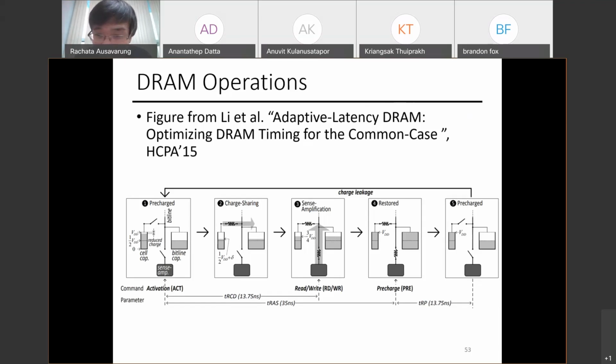Okay, so can we only write data on the DRAM row? Yes. You need to write the data on the row buffer, and then you need to pre-charge, move the data back to the row. So the way you write something to DRAM is this. Basically open the row, bring that row's data onto the row buffer. Write that, move it back. That's why it takes a long time.